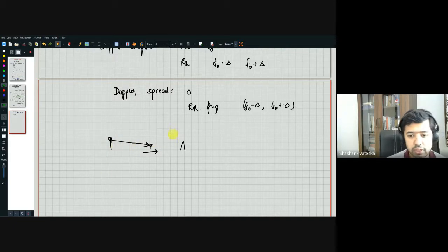But on the other hand, if there is a reflector somewhere else, then there's one more component which is reflected off this particular object and received by the receiver, and this in some sense behaves like another source. All right, so it is a reflection, but in this case you are moving away from the source, whereas in this case you are moving towards the source, and that is why the signal that is received is not a single frequency anymore. This could be a range of frequencies.